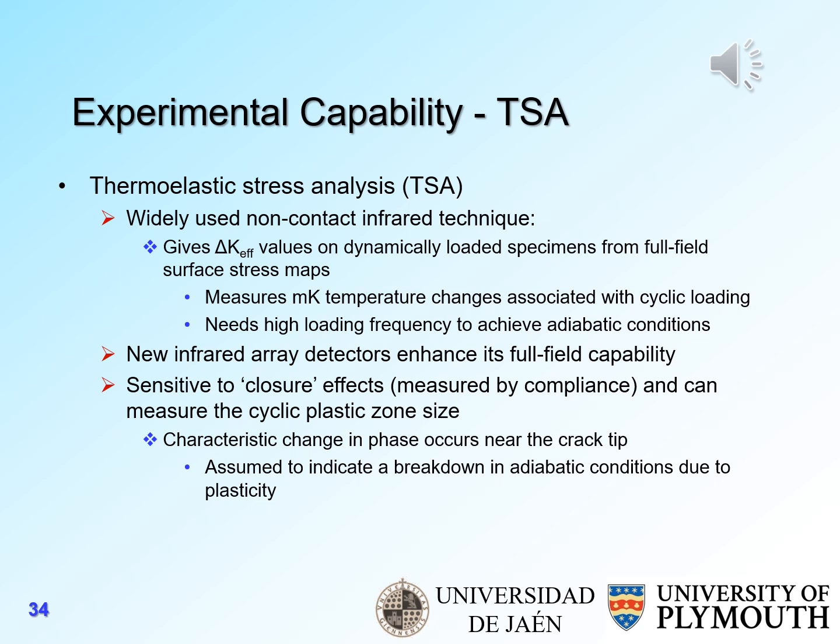Moving on to considering experimental capabilities of thermoelastic stress analysis, it's a widely used non-contact infrared technique, and it gives you delta K effective values on dynamically loaded specimens from full field surface stress maps. You measure millikelvin temperature changes associated with cyclic loading, and you need a high loading frequency to achieve adiabatic conditions.